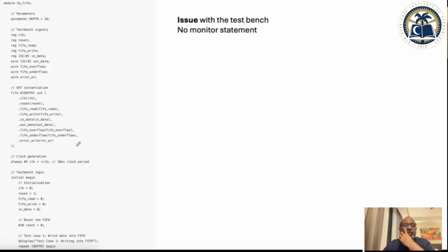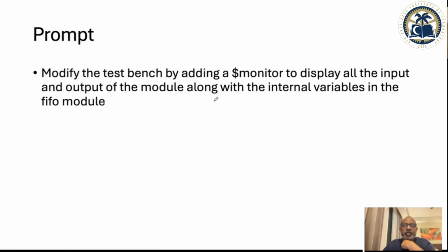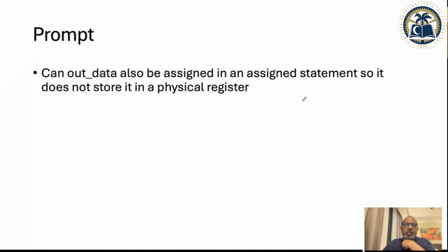I ran it, and I did not like it. I asked it to put a $monitor to display all the inputs and outputs of the module along with the internal variables in the FIFO module. And I also asked that out data should not be assigned to a register, it must be outside the procedural block.